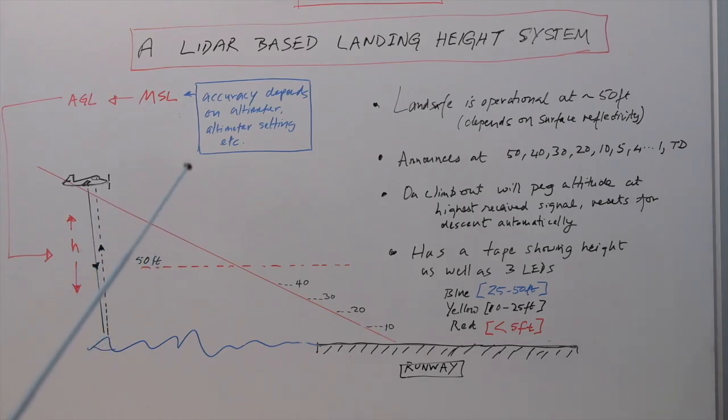ground. So this is an exact height above the ground, down to probably in the order of inches or fractions of a foot, that is used for landing aircraft with high accuracy under conditions that may not be very good for visual conditions especially. So the main thing we need to talk about here is the different types of altitudes that we talk about in terms of aircraft, whether it's above the ground or whether it's above mean sea level. So that it tells you the height above a certain plane.